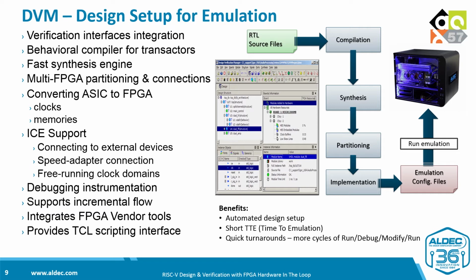If you plan for in-circuit emulation, ICE, it requires connection to free-running clocks or external devices. DVM facilitates connection of such modules too. An important part of emulation is hardware debugging. During design setup, DVM tool provides source code instrumentation to preserve all required design internal signals and integrates the design with debugging infrastructure.